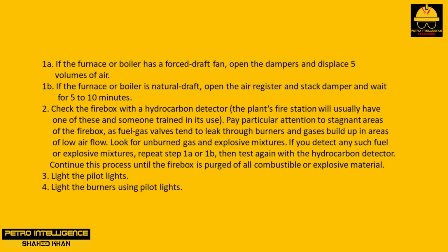Look for unburned gas and explosive mixtures. If you detect any such fuel or explosive mixtures, repeat step 1A or 1B, then test again with the hydrocarbon detector. Continue this process until the firebox is purged of all combustible or explosive material. 3. Light the pilot lights. 4. Light the burners using pilot lights.